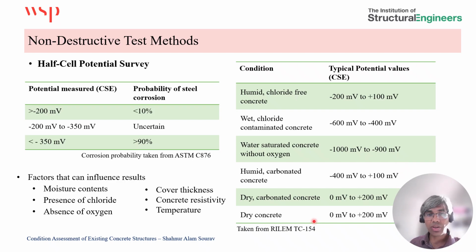In the case of dry concrete, the potential values will usually be towards the positive side. So in dry concrete, if there is limited water present, there will be limited corrosion as well.